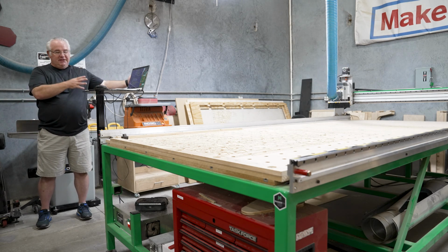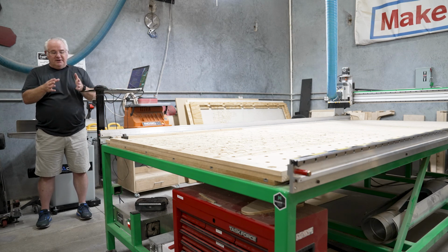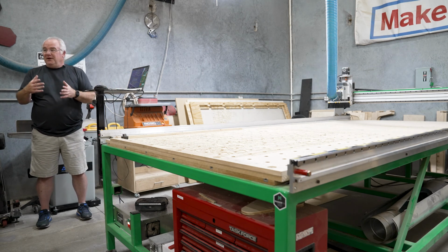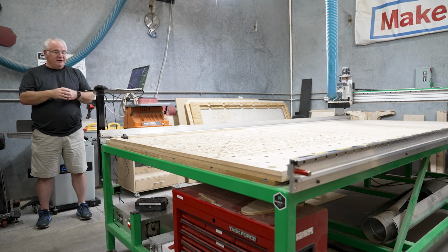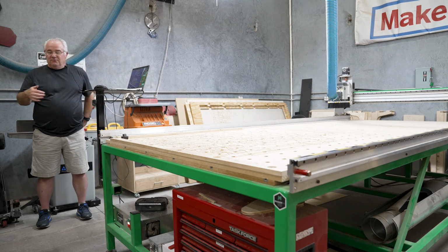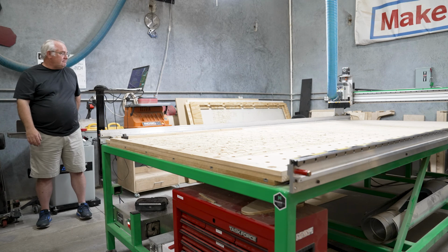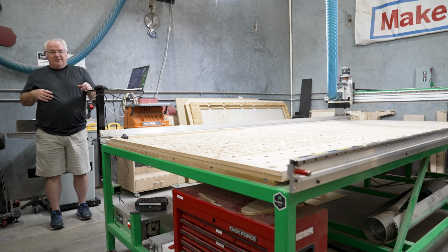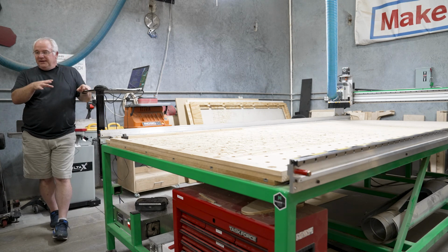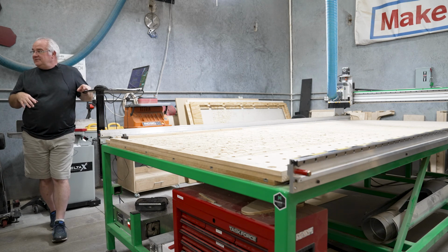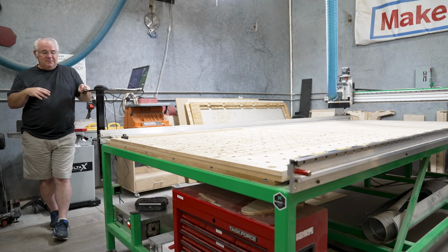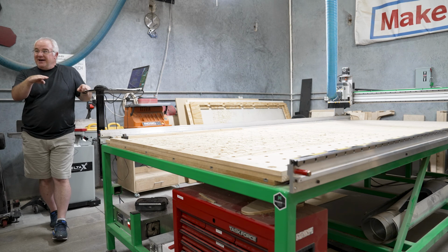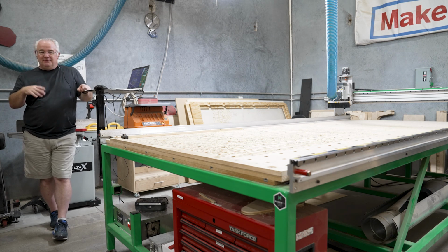But there's the machine home position, and then the other is going to be our job home, wherever we mount our material and actually ask it to run the job. And what we're going to do today is we're not going to put any wood up just yet on the first pass. I'm going to show you how to set the job home kind of artificially high, and we're going to run a job, a 20-minute job that we use to cut on a 4x8 sheet